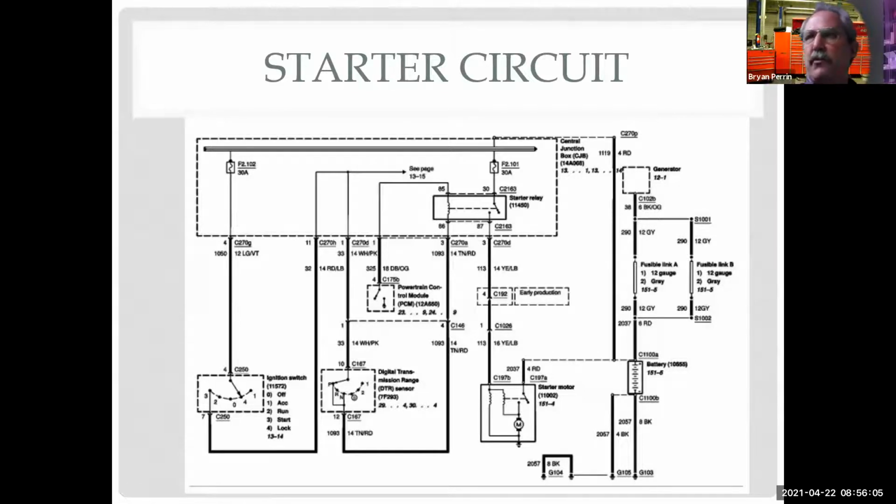So you see why that relay is, I mean, it's easy to get to, and it divides the circuit into 4 different sections very quickly and allows me to test those sections very quickly. So you can see why I really like relays, is because it is just such a great test point.